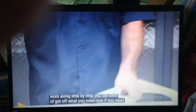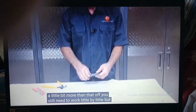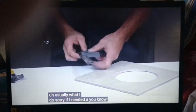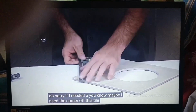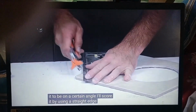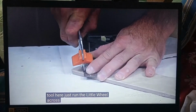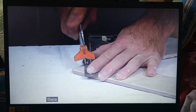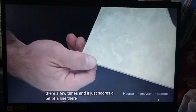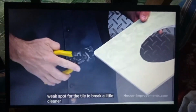Now if you need a little bit more than that off, you still need to work little by little, but usually what I do, if I need the corner off this tile but I need it to be on a certain angle, I'll score it by using a straight edge and this tool here. Just run the little wheel across there a few times and it just scores a bit of a line there. Creates a bit of a weak spot for the tile to break a little cleaner on.